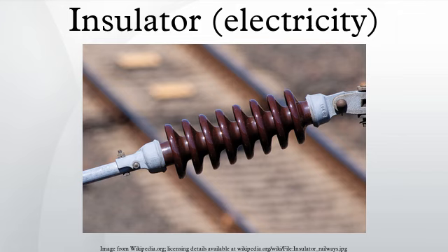Bus bars and circuit breakers in switchgear may be insulated with glass-reinforced plastic insulation, treated to have low flame spread and to prevent tracking of current across the material. In older apparatus made up to the early 1970s, boards made of compressed asbestos may be found. While this is an adequate insulator at power frequencies, handling or repairs to asbestos material can release dangerous fibers into the air and must be carried out cautiously.